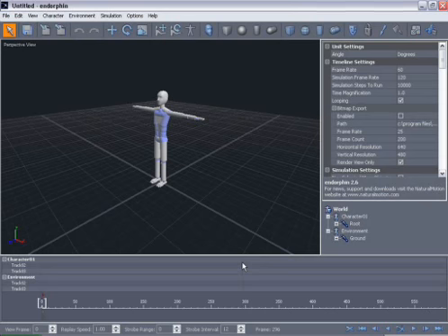Using the active animation event allows us to apply imported animation to a character while the character is still in simulation. It works in a similar way to the active pose event in that the character uses his own muscle strength to attempt to reach the position described in the imported data. The difference between the active pose and the active animation is that the character attempts to reach the pose on every frame. Because the character is in simulation, it can interact with its environment and other events on the timeline.